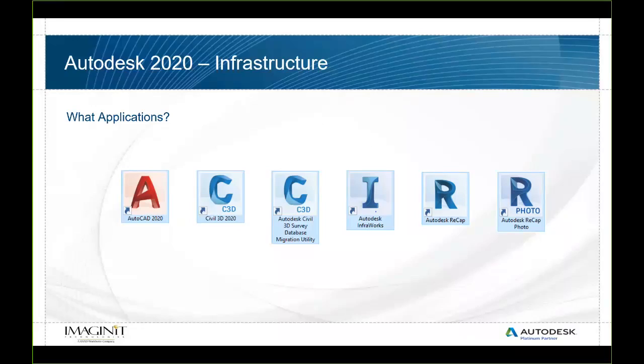There are a couple that are very, very nice. For those of you using ArcGIS, there is a save back to ArcGIS now. If you're using structures, there's a way to edit structures in a spreadsheet file instead of directly inside of Infraworks palettes. Then there's also some visualization tools that we can take a look at related to road cut and fill quantities. And then finally, just to sort of roll some current events into our presentation, we have a couple of things with Recap and Recap Photo.